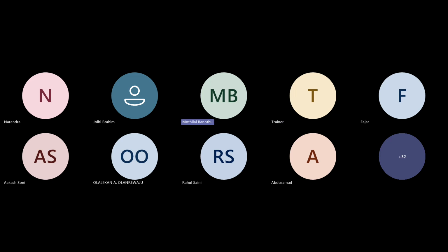So we can convert that into pressure. It is negligible. Because the diameter is big? No, no, it's because of height. If you have a 10,000 meter diameter and the liquid height is only 1 meter, then 0.1 is the pressure. Even if you have a 1 meter diameter and the liquid height is 10 meter, your pressure is 1 kg.